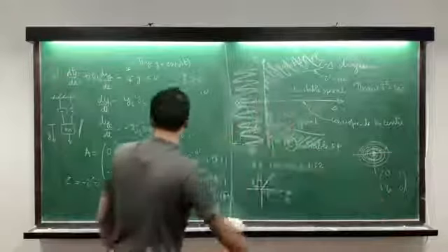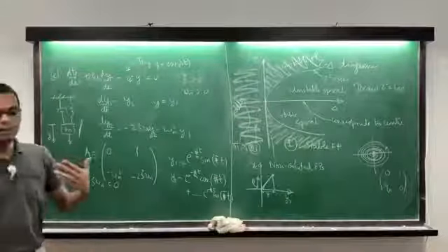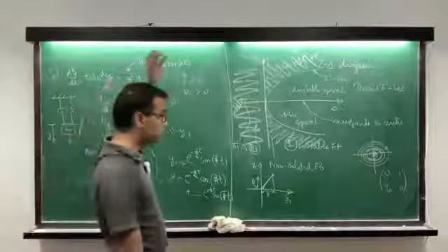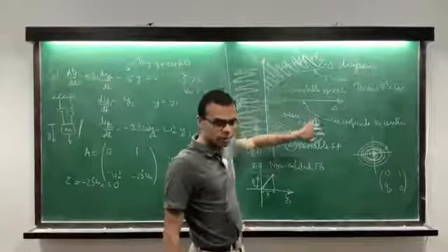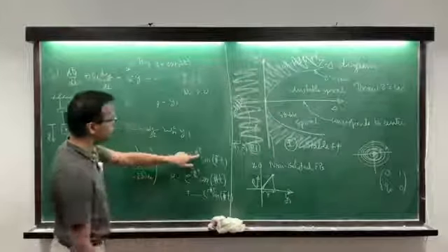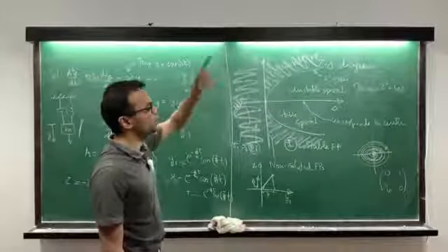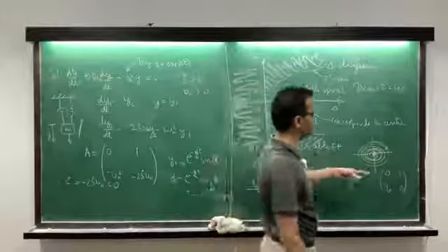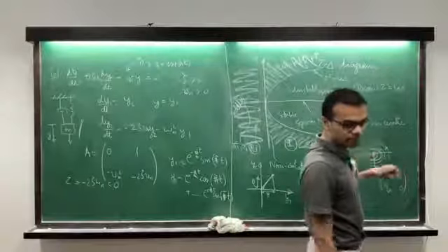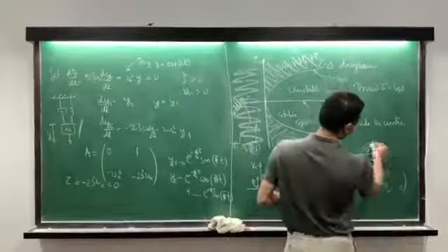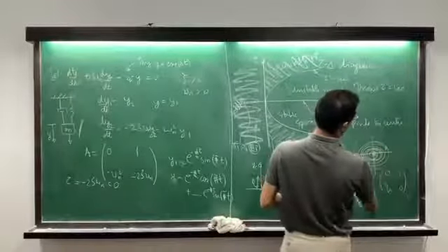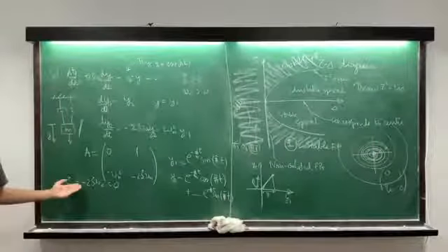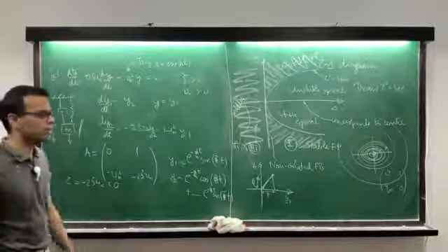If you had xi negative, which means the damping was not impeding the motion but actually aggravating it, then the system would become unstable. You can work that out as well. You will get this coefficient will now become positive, so you will get e to the power of some positive number times t. So that amplitude will start growing with t. If you start from here, you will not get a spiral coming to the origin, but you will get something that goes out. So the origin will be an unstable spiral. And that's again what this predicts, if zeta was negative, then this is what will happen.